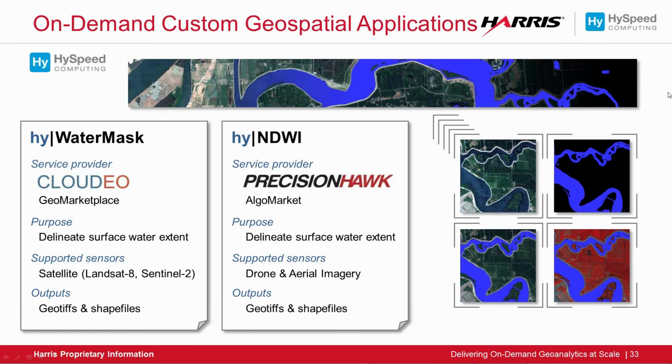water. However, with NDWI, even though you could do something similar if your system was well calibrated, it's sort of the Wild West to some degree within the drone market in terms of sensors. And so we needed to be able to work with both calibrated and uncalibrated sensor systems. And of course, there's a wide variety of them. So we used a different set of algorithms here with a dynamically generated threshold to differentiate the water features. So it uses the scene characteristics to then separate out water from land.